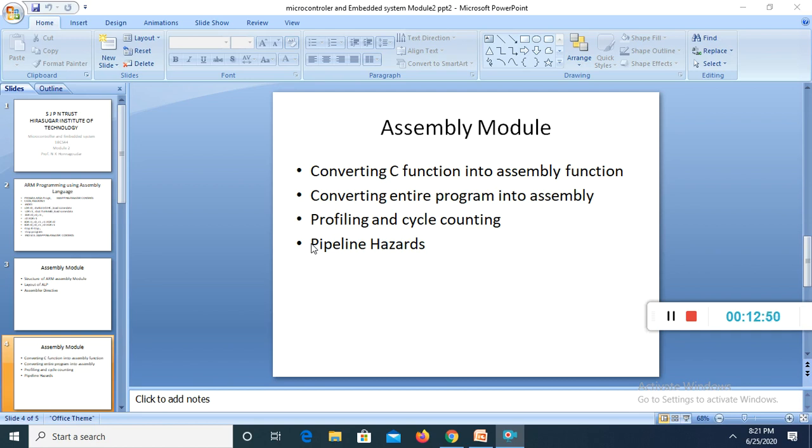Another approach is to use the trace output of a simulator as a source for analysis. To provide good results, a PC sample profiler has to take enough samples. We can even implement a PC sample profiler in a hardware system using timer interrupts to collect the PC data points. However, the timer interrupts will slow down the system.